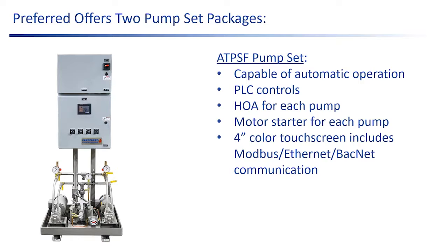You still get a hand-off-auto selector switch for each pump. And because we've got a little PLC in here and a 4-inch color touchscreen, we have Modbus, Ethernet, and BACnet communications in case the plant wants to know what's going on with their pump set.